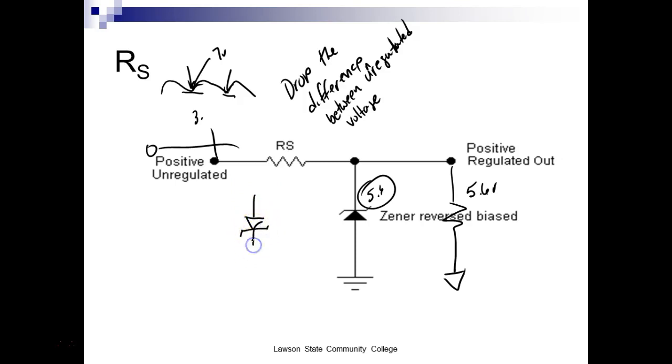And then they'll take another Zener and hook it up back to back. You'll see this a lot. What it's there for is that it clips off voltage spikes, right? You understand that? So anything above whatever the Zener's rated at, plus 7/10 of a volt, it just clips off. Like a regulator. Well, that's what a Zener is.